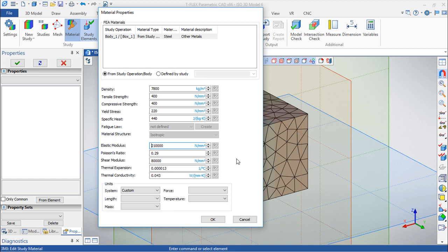Then we have another point called the yield limit, that you can find also in this diagram. And this yield limit means that further elongation of this part, or of the thing that you are testing, occurs practically with no increase of the load.